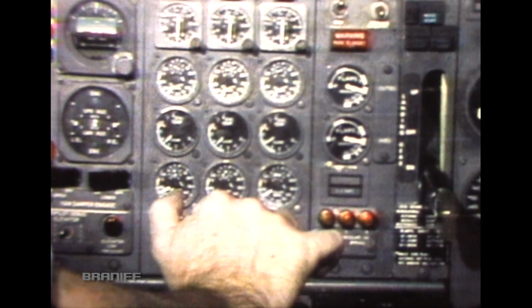In moderate to severe icing conditions, periodically run up the engines, as specified in the operations manual, to reduce the chance of ice buildup on engine probes. With low outside air temperatures, if the taxi route is through slush or standing water, taxi with flaps up. This reduces the possibility of water freezing on the flaps and restricting movement. A word of caution: do not accomplish the before takeoff checklist until flaps are extended.